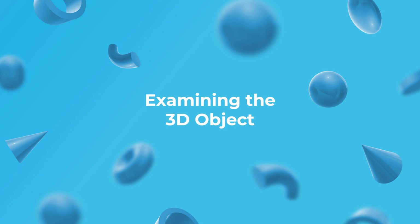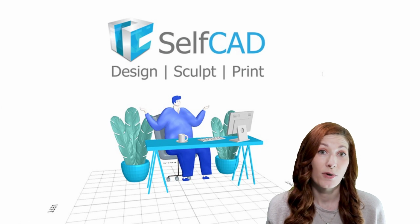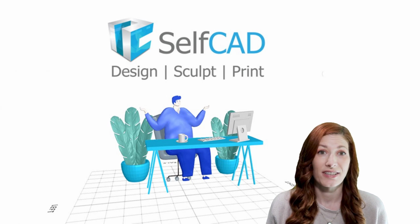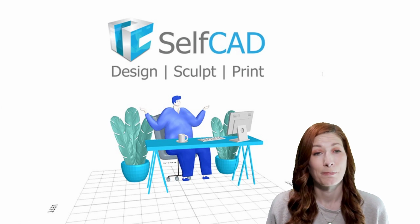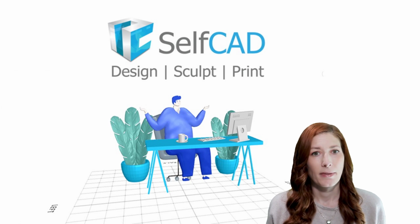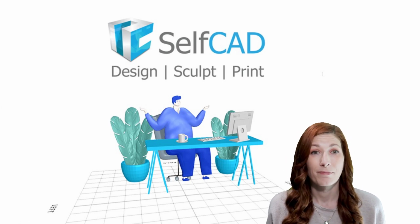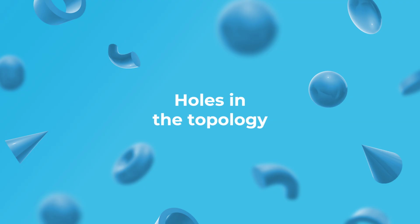Examining the 3D object. It is imperative to inspect the object after importing it to find and fix any flaws that could complicate the editing process, and in some cases even cause problems with 3D printing. The most common issues we find in imported objects are holes in the topology, flipped faces, also known as flipped normals, interfaces, and self-intersecting faces.